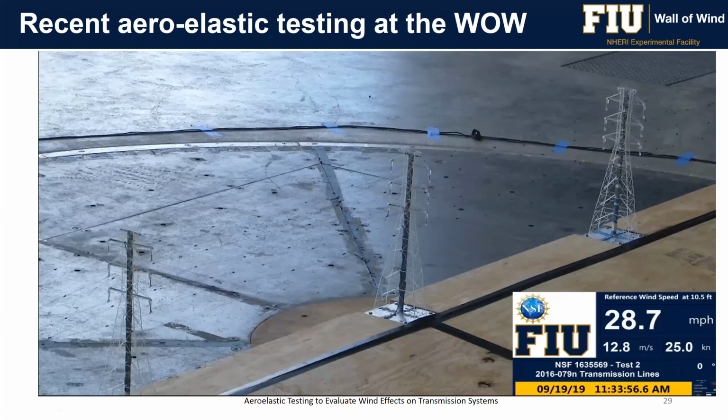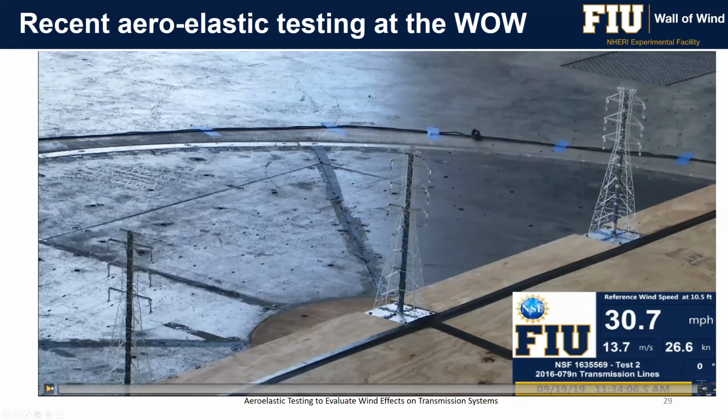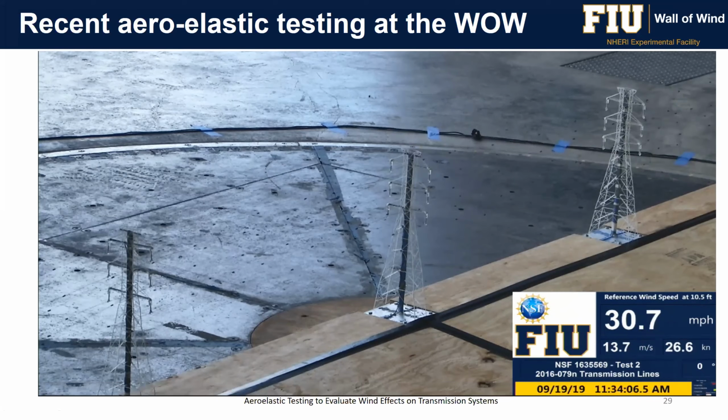Next, please. This is also a video showing the wind response of the entire system, where you can also see the cables connected between the towers. The good thing about the Wall of Wind turntable is that it's 5 meters, so we can fit this kind of multi-span structures. Here on the right, you can see the wind speed, 30 miles per hour, which in full scale, because that was the reduced-scale wind speed, was like hurricane winds. I guess it was like 100 or 130 miles per hour.